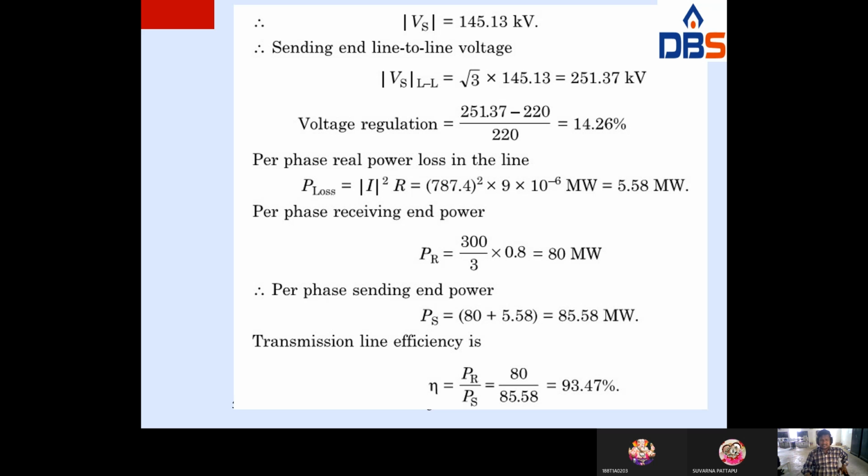So first we have to calculate the I². We know the Vr, we know the Ir, we know the cos φr. Remaining term is 3I²R. Calculating the real power loss in the transmission line is I²R per phase. Then we get the three-phase loss also.